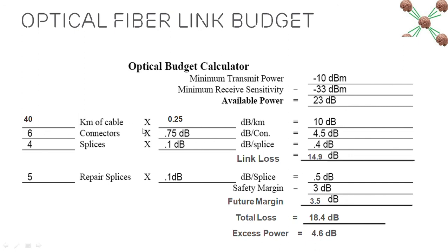So as this we saw, this was a length of 40 kilometers, which is a very typical length within a city, and even for a big city, 40 kilometers is a very typical length. And if you have a normal fiber of 0.25 dB per kilometer, it means that your transmission loss is basically only 10 dB.